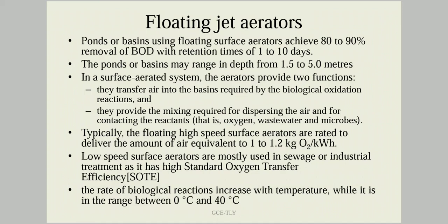One is the transfer of air into the basin, which is required by the biological oxidation reaction. So we transfer the air into the basin, which is required for the biological oxidation process to take place. The second is that they provide the mixing required for dispersing air and contacting the reactants. So first, it provides the air into the system so that the biological oxidation reaction can take place.